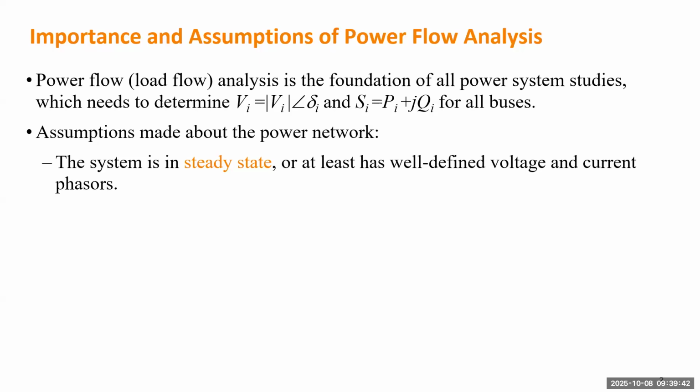It doesn't affect the concept of voltage phasor. We still can utilize voltage or current phasors to represent the waveform. So we still can do the power flow analysis on such a model. So the requirement will be, ideally you want to have the system in steady state. If it's not perfectly in steady state, it needs to at least have well-defined voltage and current phasors. That's a bottom line requirement. If you have well-defined phasors, you can utilize all the methodologies and models we're going to talk about in this section.